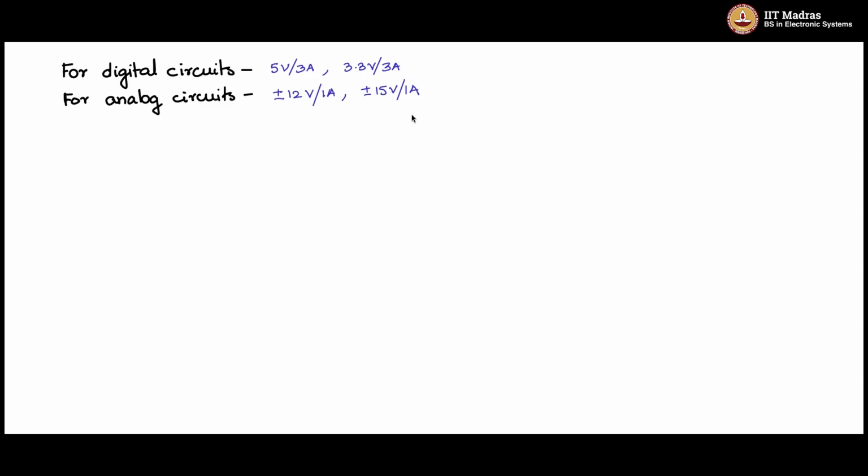So let us see how a power supply circuit looks like. We will first develop a linear power supply. Quality wise, the linear power supply gives outputs that are of very high quality in terms of performance, in terms of ripple rejection, in terms of regulation. And therefore, when you are talking of high precision electronic systems, go in for a linear power supply. If you are looking for compactness, then go in for a switched mode power supply. First, let us look at how a linear power supply looks like. Let us design that.